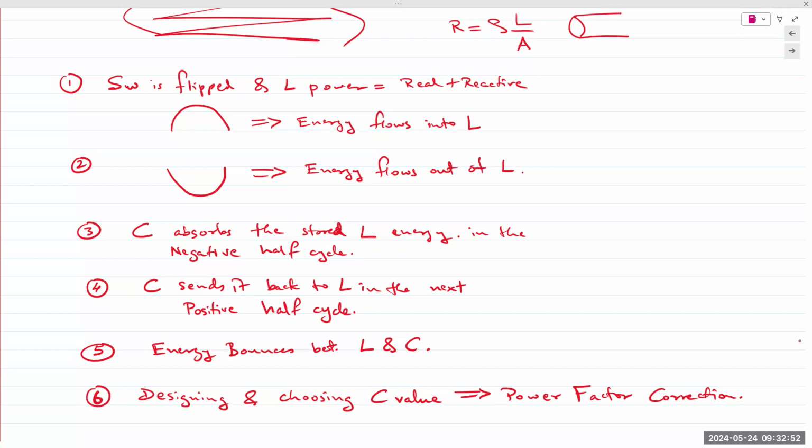Going back to the last topic of chapter 6, resonant circuits, that is what happens. If the system is perfectly balanced out, you have a resistor, capacitor, and inductor in a circuit, there's always going to be a resistive load, right? There's always a portion of the load that's resistive. If the energy that is required by the inductor or the capacitor is perfectly balanced between the two, what happens? The energy is now just bouncing around back and forth between the two. They do not pull any energy from the source. All of the energy coming from the source goes to that resistor.